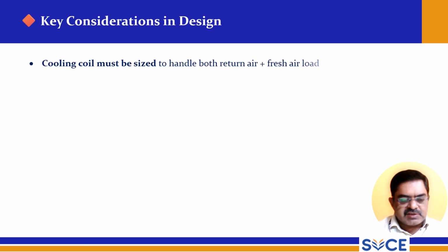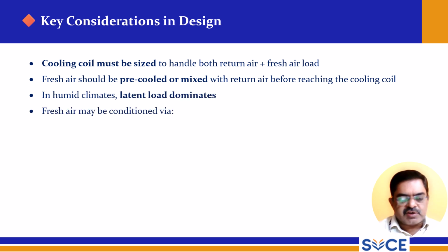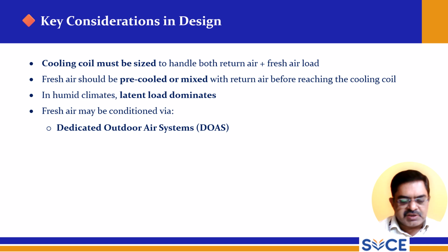So key considerations in design: the cooling coil must be sized to handle both return air as well as fresh air load, and fresh air should be pre-cooled or mixed with return air before reaching the cooling coil. And in humid climates, latent load dominates, so fresh air may be conditioned via dedicated outdoor air systems, that is DOAS, and heat recovery ventilators, HRVs.